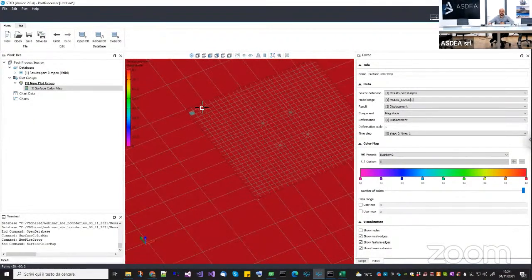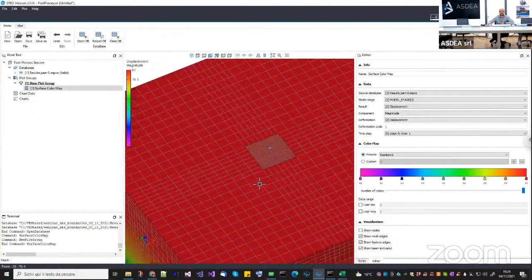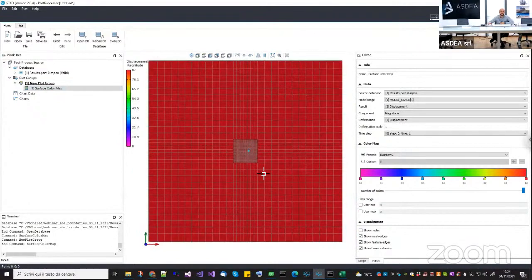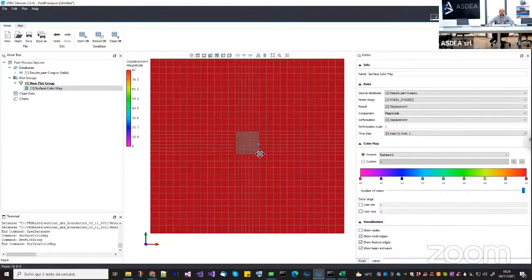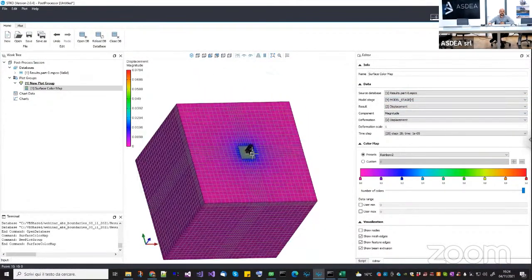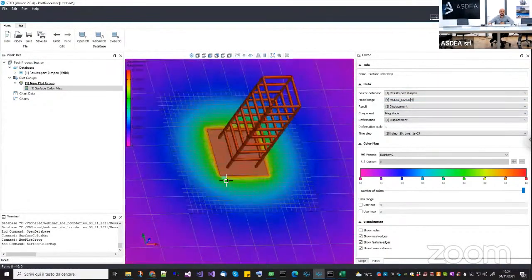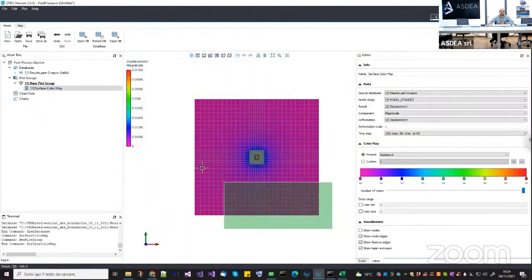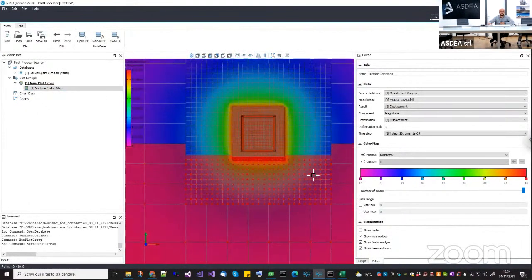connecting non-conforming meshes. Okay. Or probably it's easier if I switch on every. Let me go to the final stage. Okay, and I want to cut the model here in the middle so that you can see also the piles. So I want to hide part of this geometry and also up to here.